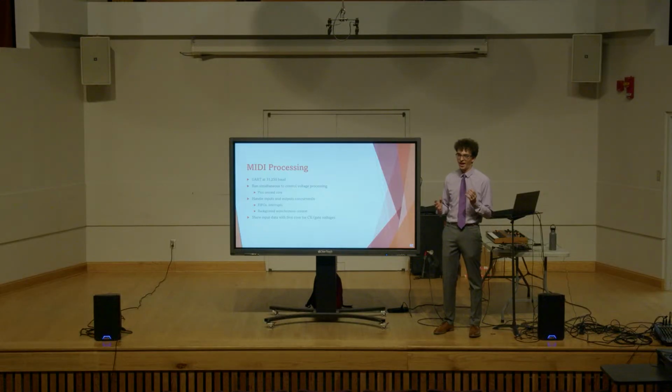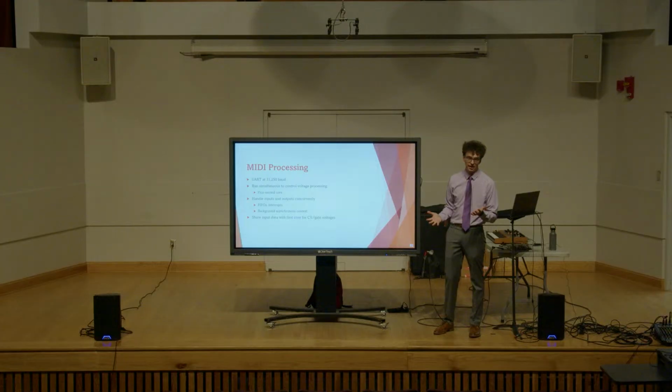So I did not want to have to run these serially. I didn't want to have the MIDI processing, reading a MIDI signal or sending a MIDI signal, take up time on the processor that was running the SPI to the DAC. So this is where I started to implement multi-core design and threading on the Pico, so I could have the first core doing all the control voltage processing and the second core doing all the MIDI processing. And these allow me to do these simultaneously without interfering with each other, unless I tell them to.